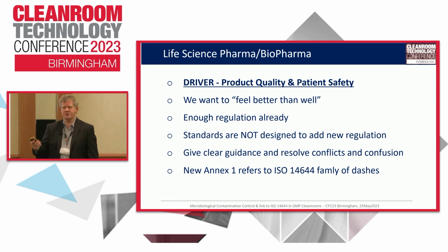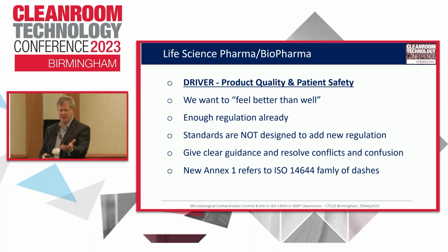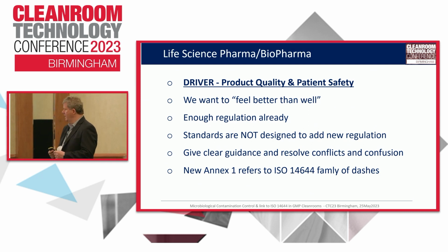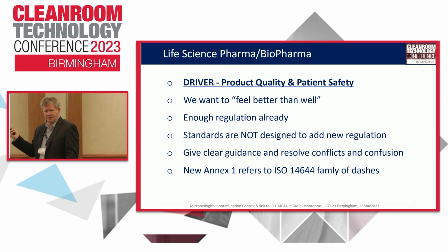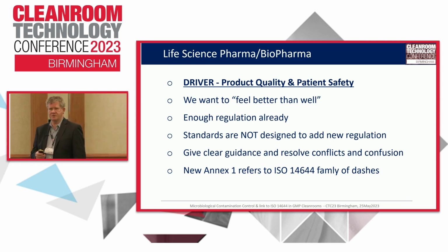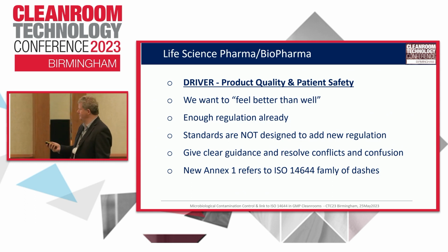There's enough regulation in the world today between aseptic guidance from FDA 2004, the new Annex 1, which is now a PICS document, so it's now worldwide for all the countries involved in the inspector cooperation scheme. And the good news is the new Annex 1 refers to 14644, of which there are many dashes. That's the bad news, which I'm going to show you in a moment.